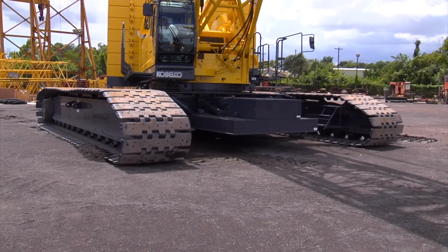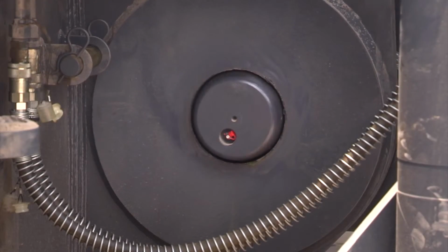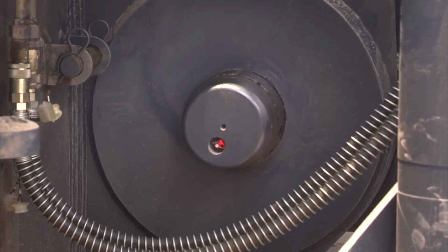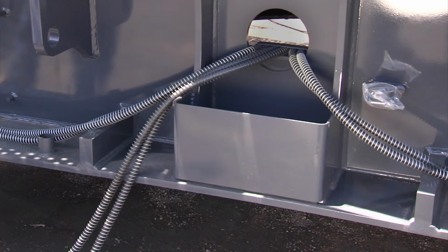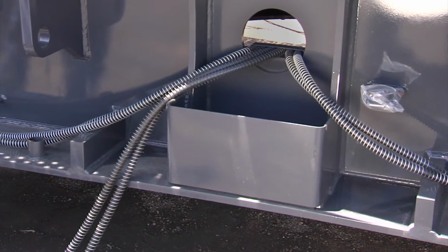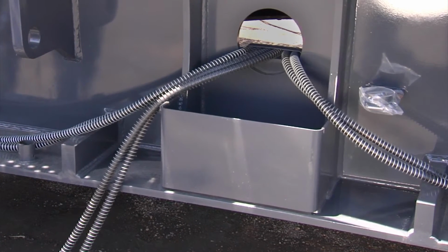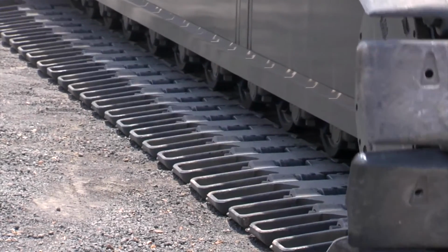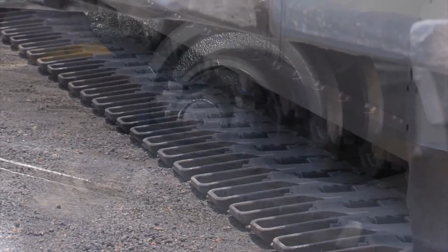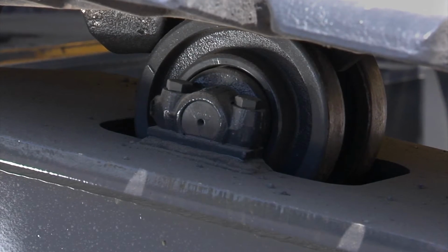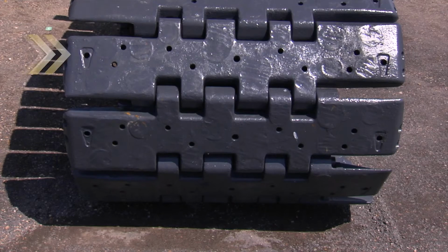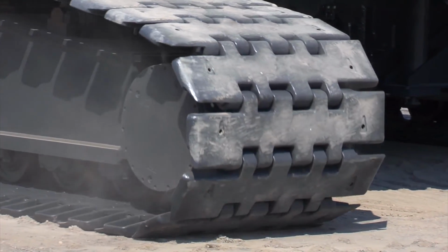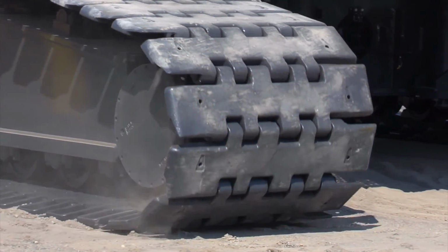The crawler frames on the CK2750G are held in place with 2 hydraulically controlled pins and 2 fixed pins. The hydraulic hoses with quick connects for operating the translifters or the track connecting pins are stored in the center of both sides of the base machine. The crawler frame assemblies feature track rollers that are oil sealed and do not require greasing. The track pads have arrows cast in them to indicate the forward direction of the tracks visually from the operator's cabin, to quickly remind the operator the direction the crawlers are facing.